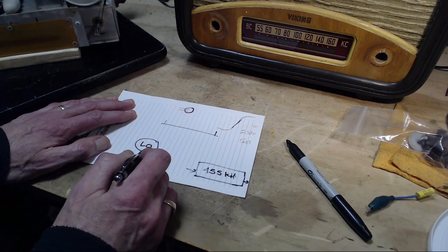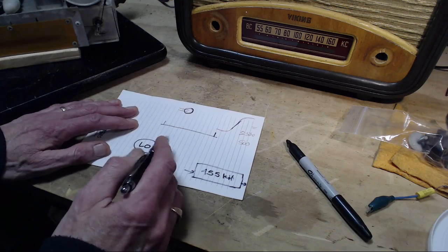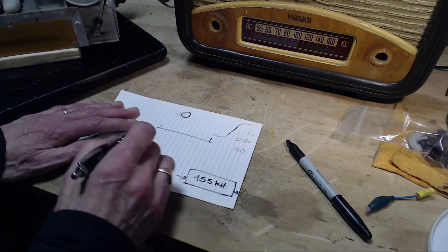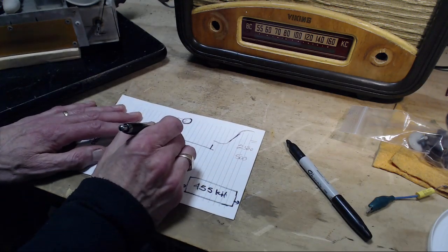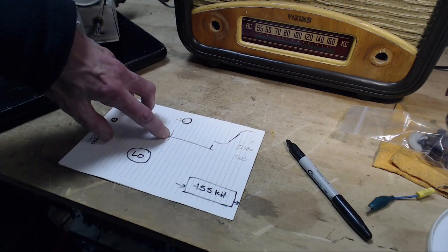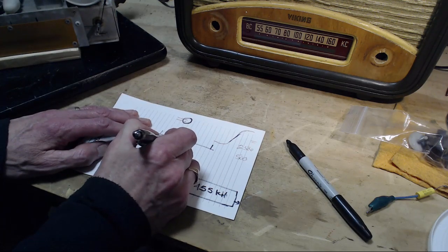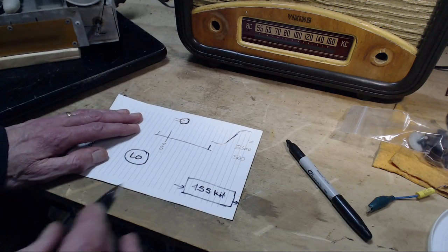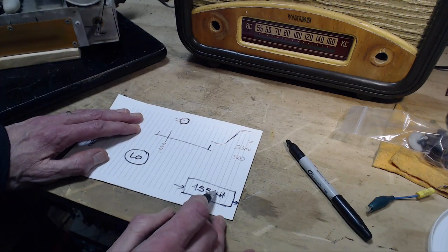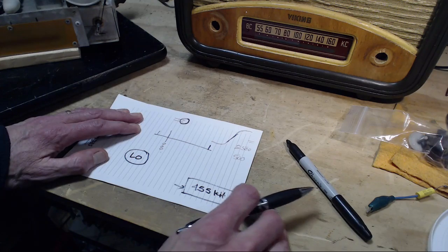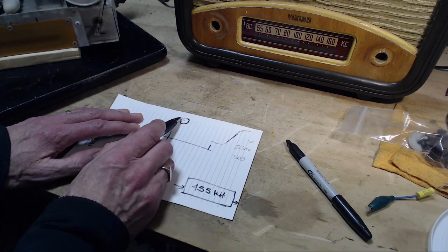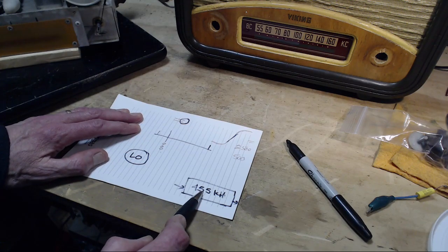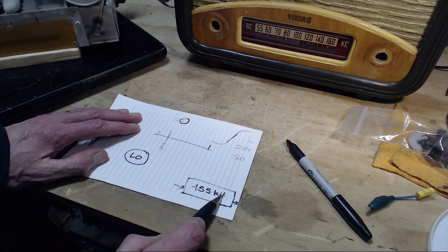Now, how do you use a local oscillator to do this? Let me give an example. Let's say we want to tune in this signal here. Let's say this is 900 kilohertz. Got a nice radio station there. And we want to get the 455 to go through the rest of the radio. So we can stick two signals on here that are 455 kilohertz apart. They will produce a 455 to go through there.